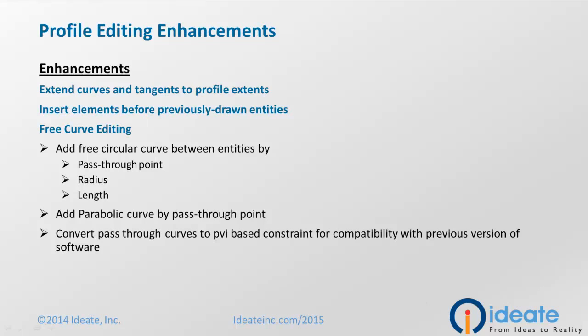In addition to the ability to lock the profile to horizontal geometry, which was covered in another of our videos, there are new profile editing enhancements. The first is the ability to extend curves and tangents to profile extents. Also, you can insert elements before previously drawn entities. And lastly, there are new options for free curve editing.